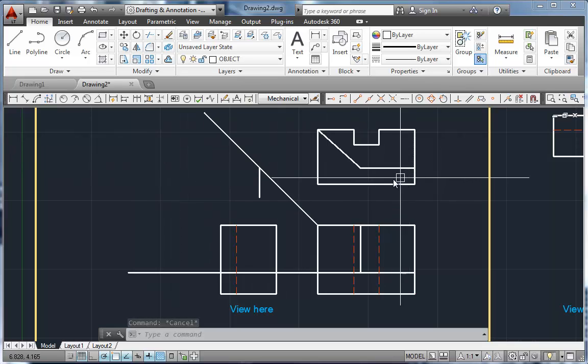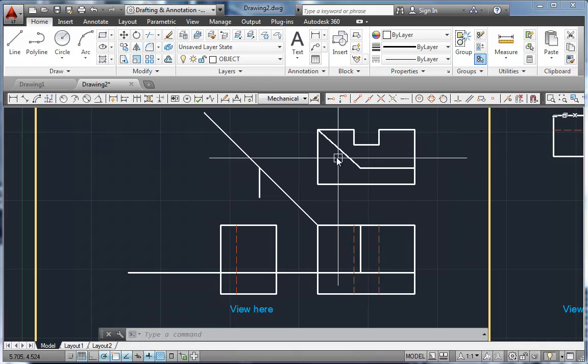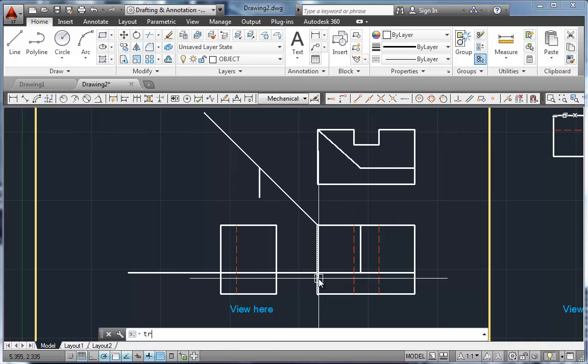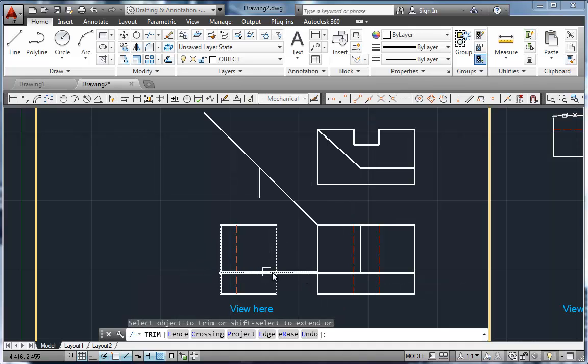Okay, now I have a surface here. I can see it. This is an open space here, and I have to assume, because it's got a bounding box around it, that it's a flat planar surface, because all I see in this view is a flat line. So I have a flat planar surface, and that surface starts at the front of the part here, and it ends right back here in this corner. So that surface goes all the way back to here. So when I look in from the left side of this thing, I'm going to see that surface going from front all the way to the back. So that line goes all the way across the view. So I'm just going to go ahead and trim and snip those off.